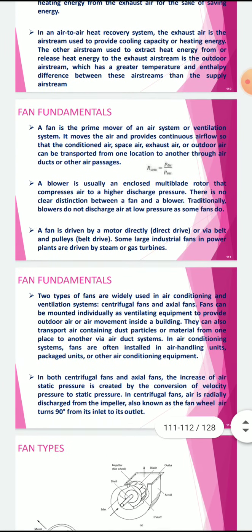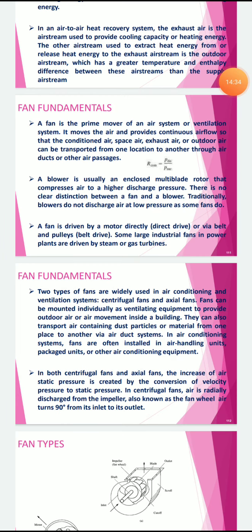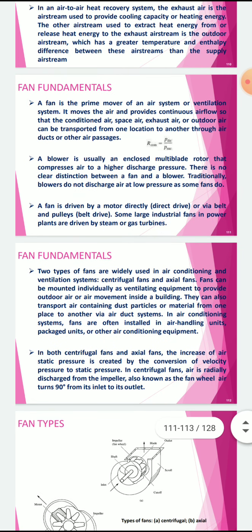Now we need to discuss fan fundamentals. Fan is also required for blowing the air. A fan is a prime mover of an air system or ventilation system. It moves the air and provides continuous airflow so that the conditioned air, space air, exhaust air, or outdoor air can be transported from one location to another through air ducts or other air passages.